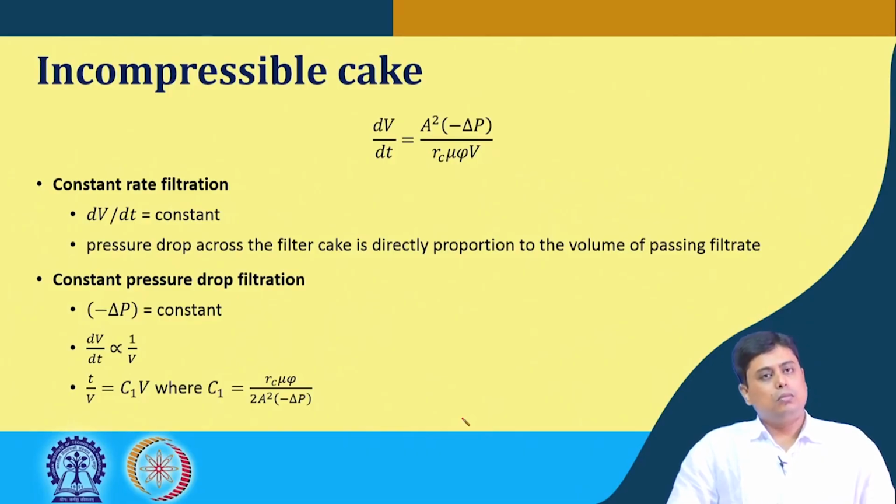Under this cake filtration, as I mentioned earlier in the last class, if you appreciate the scenario where you have to maintain a constant rate of filtration, then the pressure drop across this filter cake is directly proportional to the volume of passing filtrate.